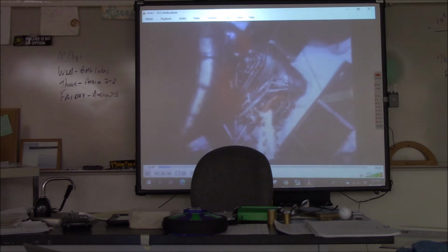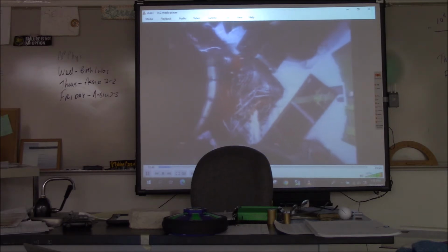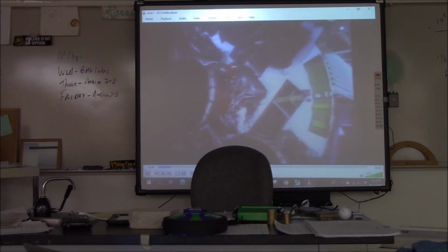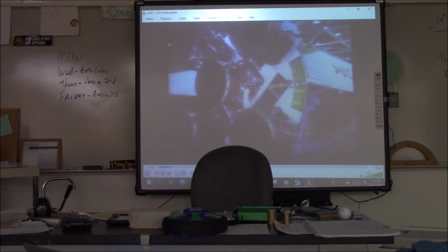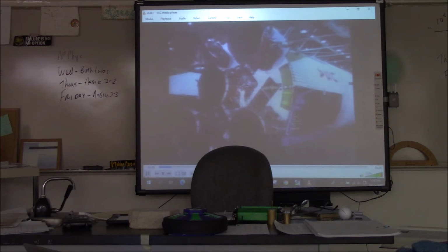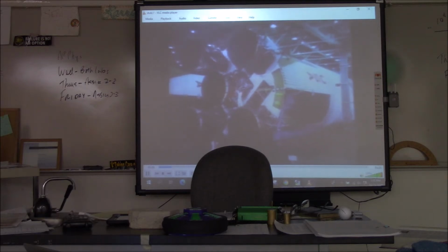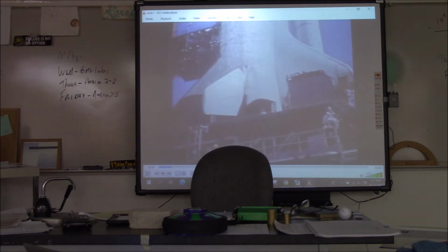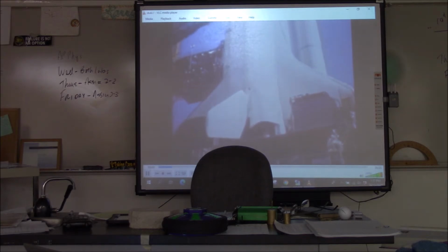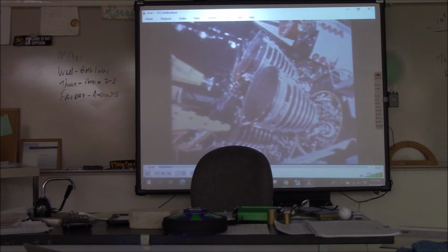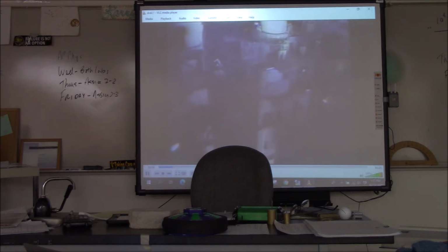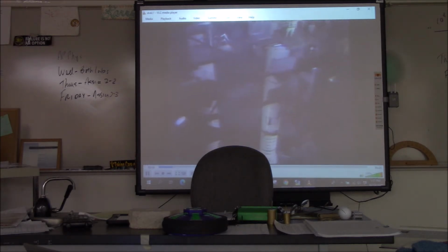The single most important component of a launch vehicle is the rocket engine. Use of a rocket engine provides the means by which thrust is produced in the vacuum of space. Since oxygen is not present in a space environment, an oxidizer must be carried on board the rocket along with the fuel. The Space Shuttle's propulsion system is made up of 5 different rocket engines, 3 main engines which use liquid propellant, and 2 rocket boosters which use a solid propellant.